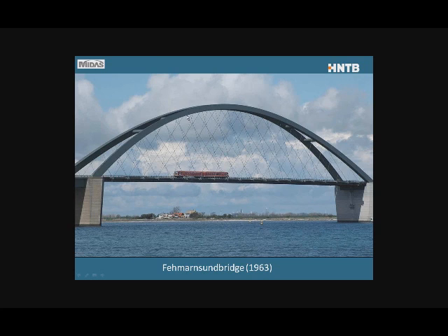A network-tied arch is characterized by the set of inclined cables. You can see here two sets of cables in each cable plane. So instead of vertical, like the conventional tied arches, they're inclined. And the crucial part of the definition is that some of these cables have to cross at least two other cables. So if I take, for example, this cable here, that's actually being crossed by 1, 2, 3 other cables. So that's what makes a network-tied arch a network-tied arch.